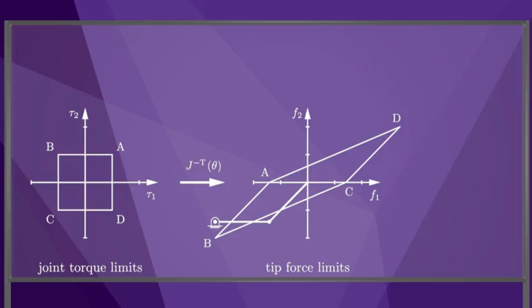In this configuration, the arm can apply large forces up and to the right at point D, but much smaller forces up and to the left. The reason is clear. A line of force up and to the right passes close to the joints, therefore requiring little torque about the joints, while a line of force up and to the left passes far from the joints, requiring larger torque. In the extreme case, if my arm is extended straight out at a singularity, I could theoretically resist infinite forces applied along the arm because the forces pass through the joints, creating zero torque.